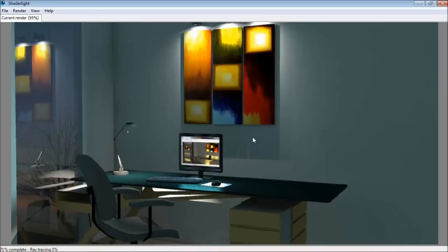If the model has a much higher polygon count, more detailed modeling geometry in the room, would it take longer to render using lighting interiors? The simple answer to that is yes, purely because the light has to work out the number of faces, how it is sitting, how it's reflecting. The larger the scene, yes, will extend your render times.